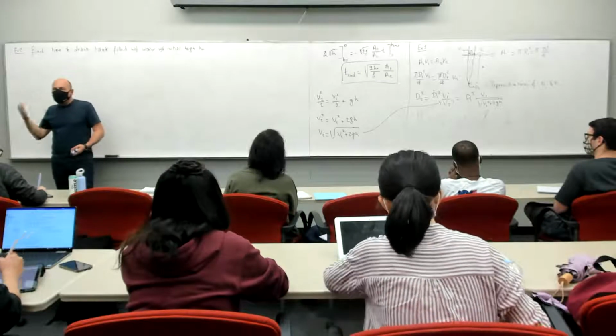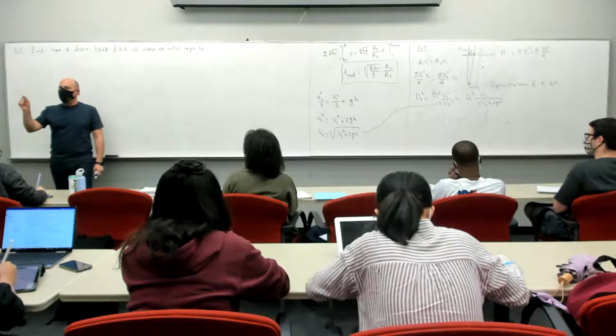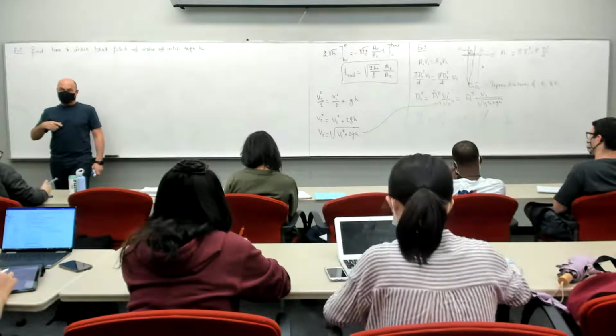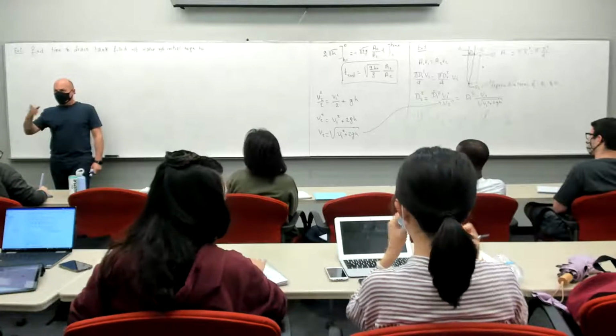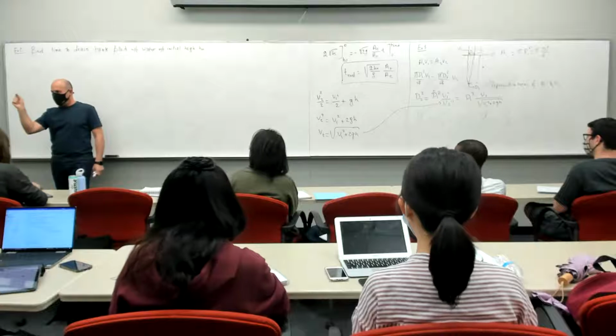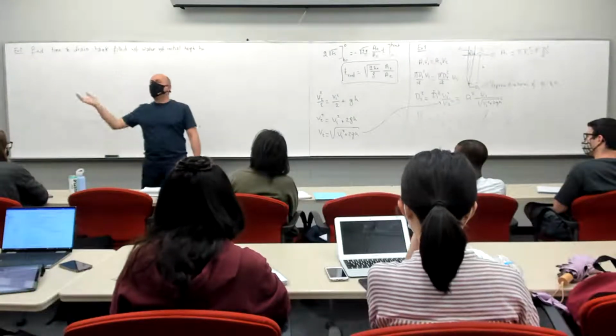So then you start seeing a trend. If you're calculating an area, a thickness, a length, you need mass conservation, okay? And momentum, because momentum is going to give you the missing piece, one of the velocities. If you're only looking for the velocity, you need momentum.